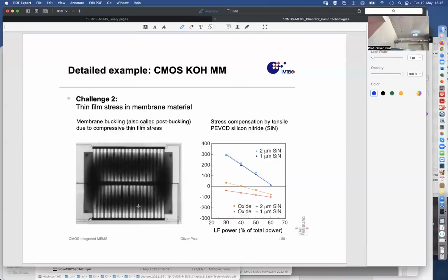The membrane wants to be released, on the silicon. It is stuck, it cannot do anything, but as soon as the silicon is gone, it does what it can to release its strength somehow. But if that release is too strong, there is too much curvature, and then it makes like a fling, and the membrane is gone. And so keeping that membrane flat, or as flat as possible, is the goal.